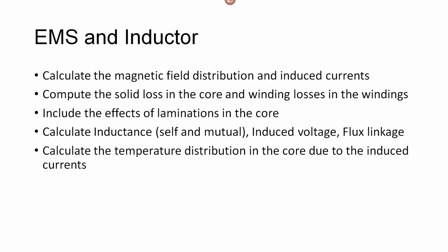Now, as far as the engineering quantities that EMS can calculate, it can calculate the inductances, the induced voltage, flux linkage, etc. All the electrical parameters and circuit parameters that are associated with inductor models will be computed by EMS. And finally, if you have a high current or high voltage situation where there is an excessive amount of induced currents in the core, one will probably worry about the temperature distribution and the heat produced as a result of this. So finally, EMS has multiphysics capabilities which couple it to thermal simulation that will help you compute the temperature distribution in the core due to the induced current. So these are some of the reasons why EMS is a good tool when you want to design and simulate inductors.